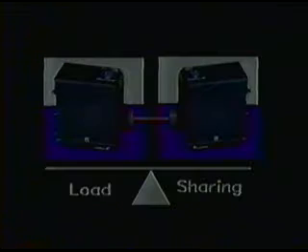When loads are removed from the bus, the generator output voltage will tend to rise. The control panel senses this and decreases the amount of field current, thereby decreasing the generator's output to the correct value. This allows the generator to produce additional electrical power to supply the bus and still maintain the proper output voltage. As the control panel is increasing the field strength of its generator, it must also look at the output of the other generator to ensure that the sharing of the load between the two generators remains equal or paralleled.